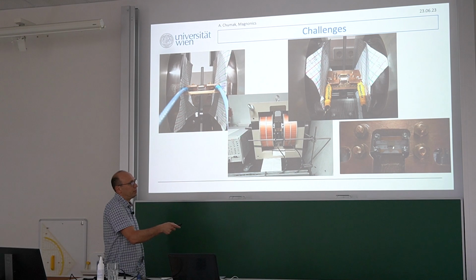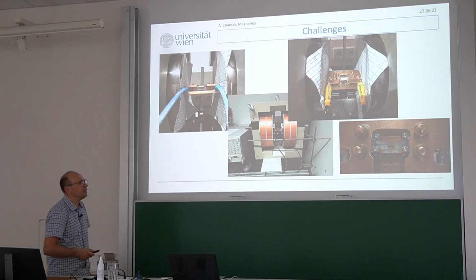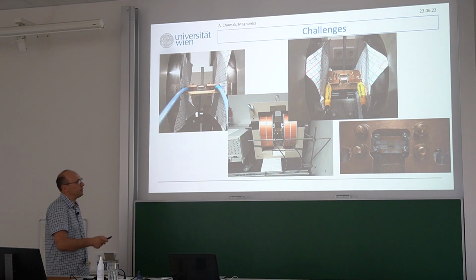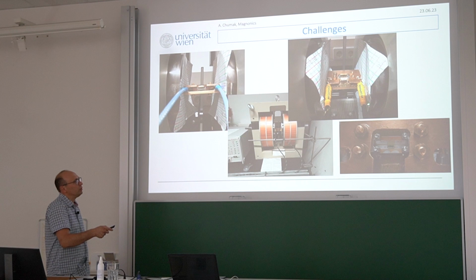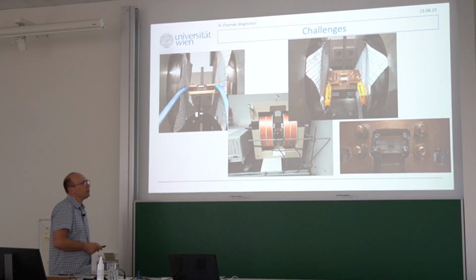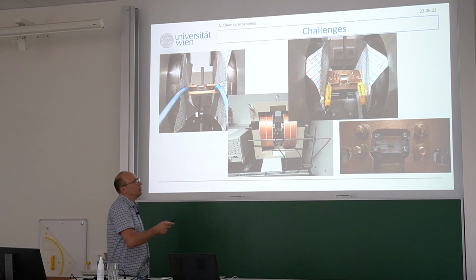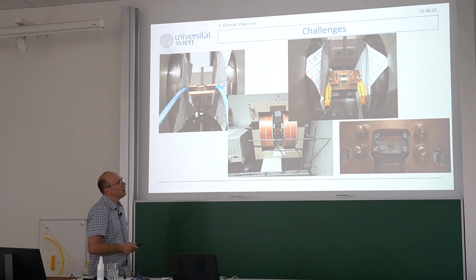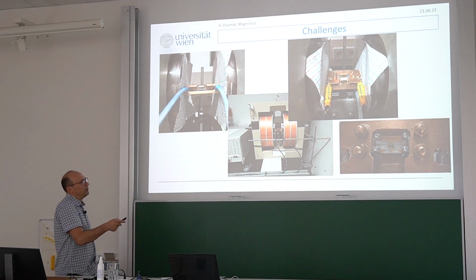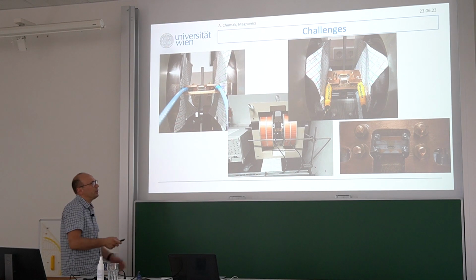The sample you see is practically transparent. It means that this is a very thin yttrium iron garnet film, maybe 100 nanometers thick. And then we have to connect this microstrip to two microcoaxial cables. Here we use SMA connectors and N-type connectors, which make more or less contact from this microstrip to the coaxial cable, one side, another side, and all this is fixed in the magnet.